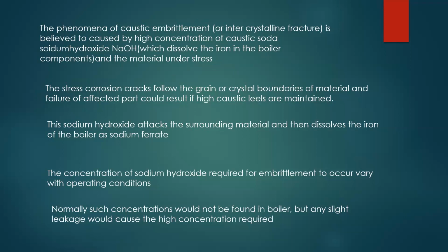Now what will happen? It makes the material under stress, and now stress corrosion will take place. The stress corrosion crack follows the grain or crystal boundary of the material, and failure of the affected part could result if you are maintaining a high level of caustic.